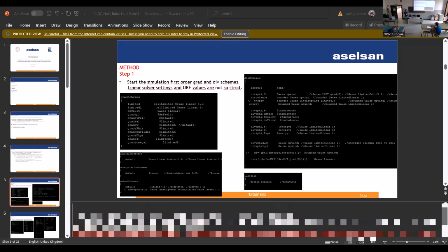Before the results, I wanna mention some key points. We have to be careful that pressure gradient is not a convection term. Central difference should be used. And for the velocity, we have to use the limiter to get a good result with the skewed tetrahedral mesh, if you are using one. So you have to be careful with tetrahedral, because for such problems, this procedure shows the performance.